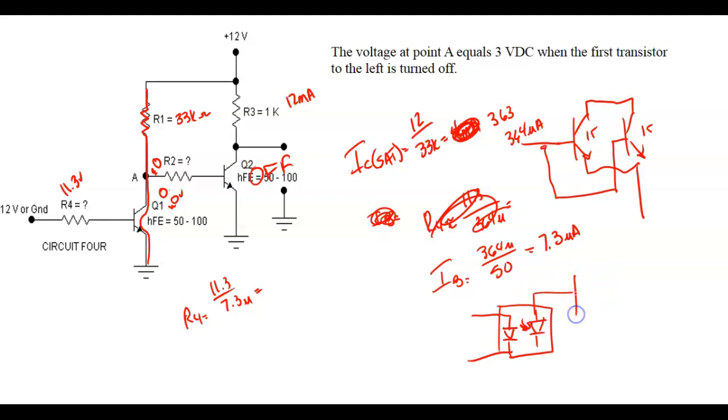And then over here, this guy would be driving a big transistor. The optical coupler keeps all this noise that's generated in an industrial complex from getting into the electronics of the actual PLC.